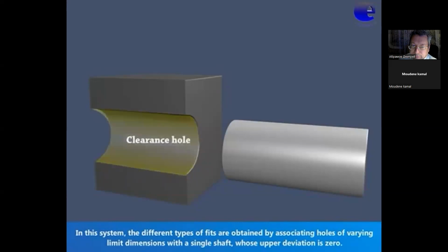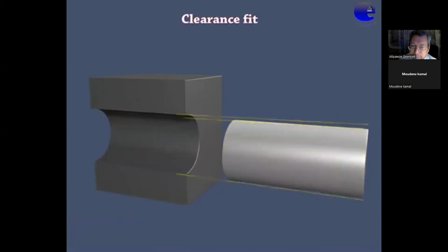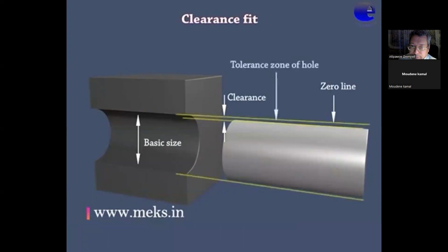Consider a clearance hole. Basic shaft, clearance fit. Basic size, clearance, 0 line, tolerance zone of hole, tolerance zone of shaft.